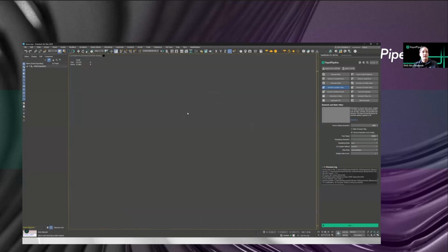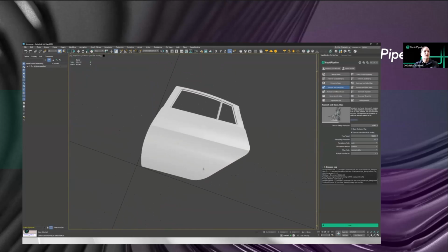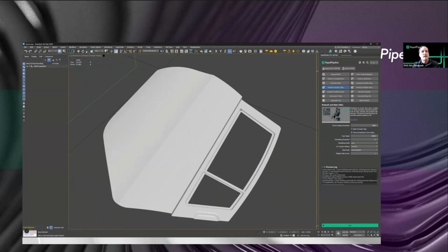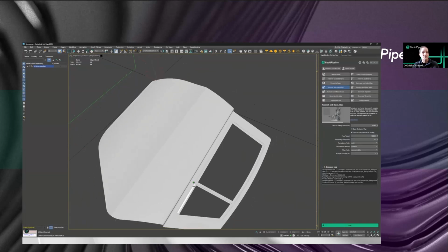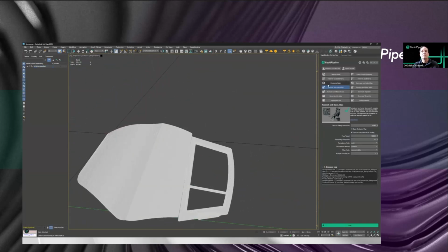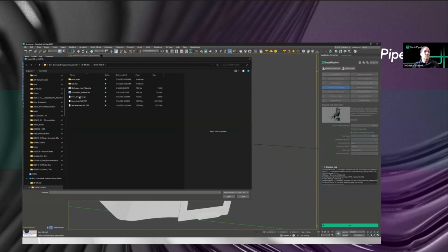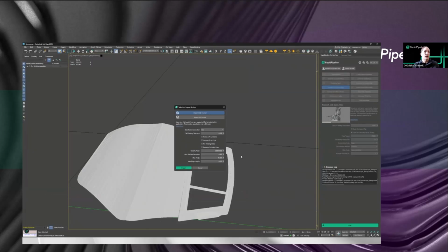So this is basically a CAD workflow. In a CAD workflow, you typically have all these little, let me turn on highlighting here so you can see, all these surfaces are separate little patches that the artist used to build this surface. And that's not that useful for me from a rendering context. I probably want to have this all be one surface. So let's re-import it, and we'll use one of those options to actually merge it automatically. And that's what the CAD sewing tolerance is all about.